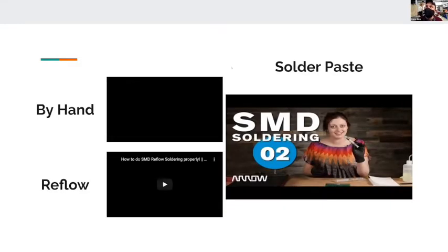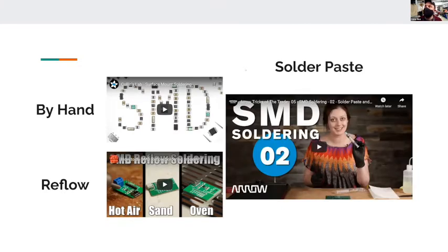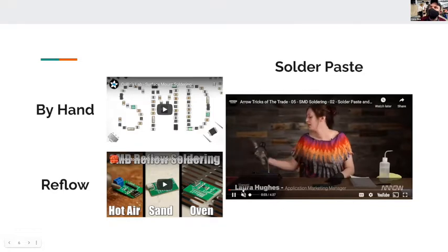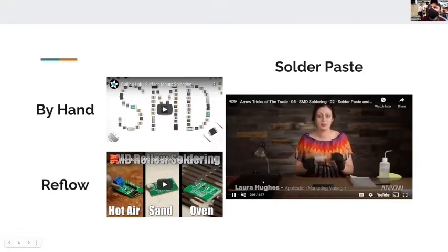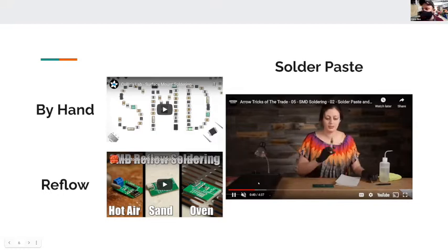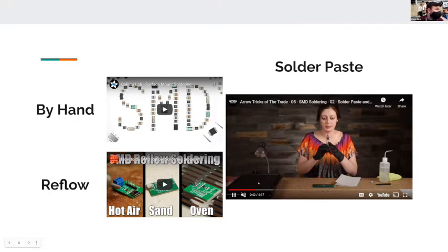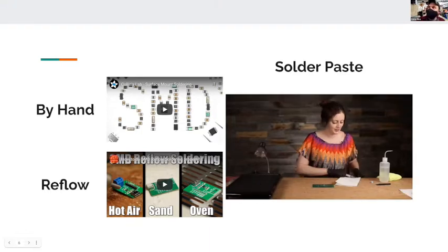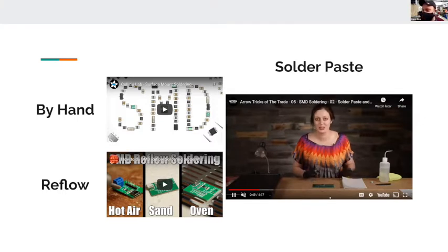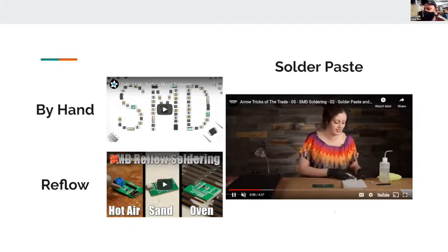Here are 3 videos that I would solidly recommend, and I'm going to let this one play without any audio. This lady, Laura Hughes, does a great job of showing what solder paste is. Here she's going to actually heat it up on a skillet, like you'd make pancakes, which is a completely legitimate way to heat up your solder paste. Solder paste also has a shelf life. It's probably another good reason why we don't use it at MakeHaven. You buy it and it goes bad after a while.